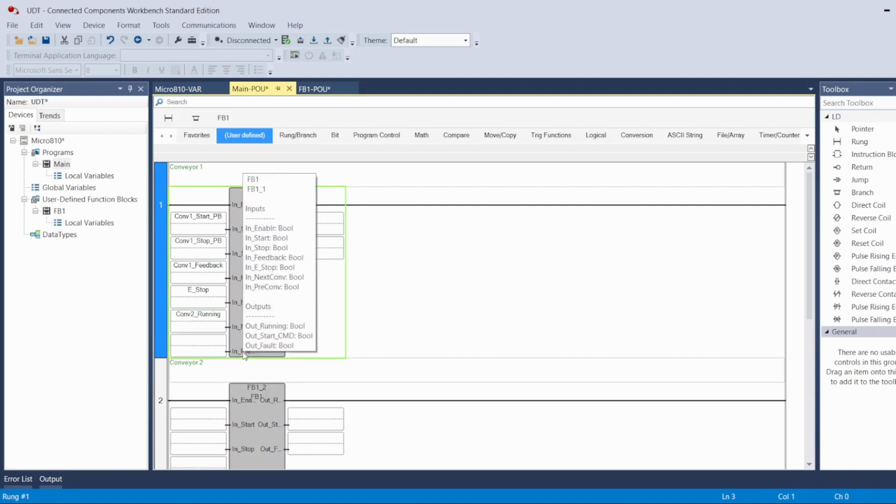Okay, am I monitoring anything previous to this conveyor? No. If there is a door closed, whatever signal you want to monitor before you start this conveyor, that's okay. But I'm not monitoring anything. If there is another conveyor behind it and I want to make sure it is running before conveyor 1 is running, I can use that. But in my case, I'm not monitoring anything for this previous signal. So I want it to be on and never turn off.